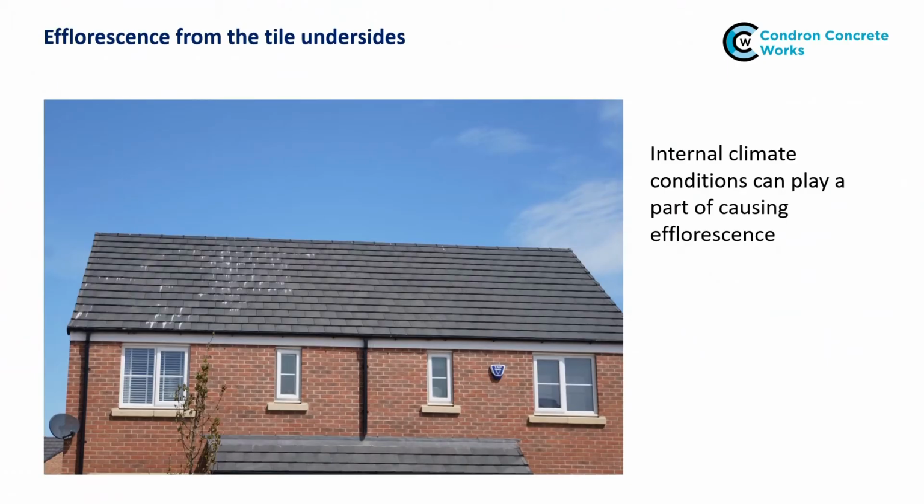Tiles have been made this way for as long as I can remember without any problems, so why is it that efflorescence is now forming on the undersides? One theory, gaining some traction, is that the large volumes of water vapour passing through the permeable underlay, particularly during a new building's drying out period, condenses on the undersides and draws the natural salts out of the tiles.